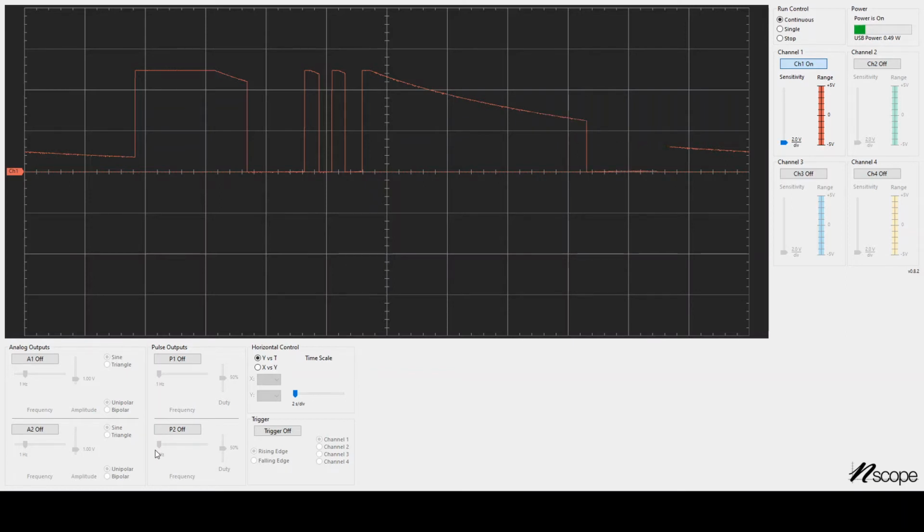So I told you that this should have a characteristic shape, the RC curve. What's happening when I hit the charge button is it charges so fast we can't even see it. So we need to zoom in time to see that shape. So I'll choose 10 milliseconds. I'll ground my capacitor. I'll push the charge button. Oh, and we saw it so fast, but not long enough on the screen. I'll just discharge. I'll zoom in a little bit more in time, push the charge button, and I just missed the event.